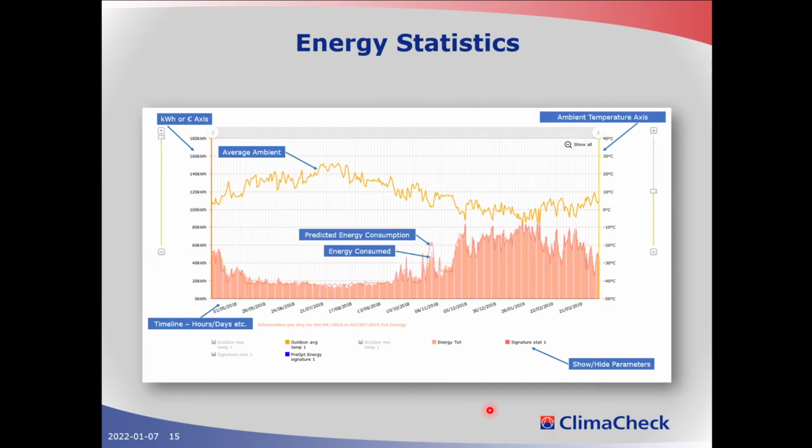There's also energy statistics on the online server. We are getting data every minute. We are measuring power input and energy consumption of at least the compressors. And many times we are on fixed, permanent installations. You are also measuring pumps or fans and auxiliary loads. And then we can show that in this energy statistics. So this is available for all the measurements you're doing with the online server.